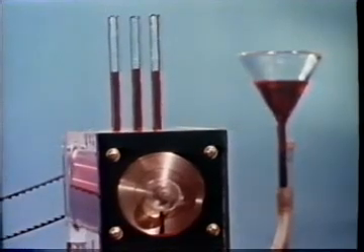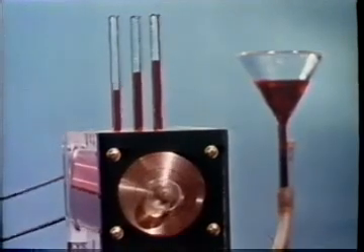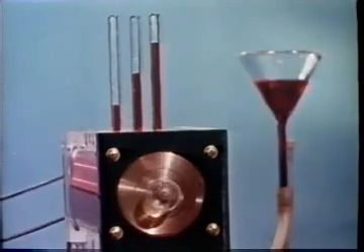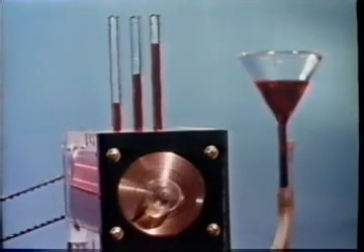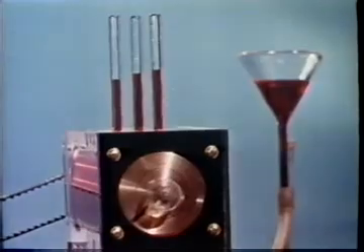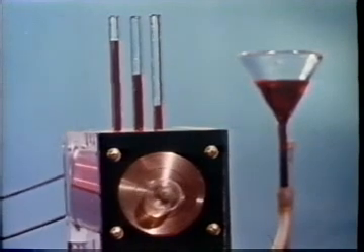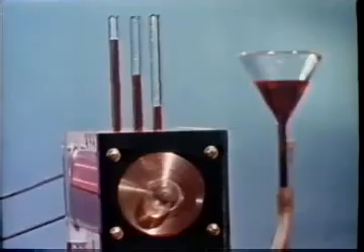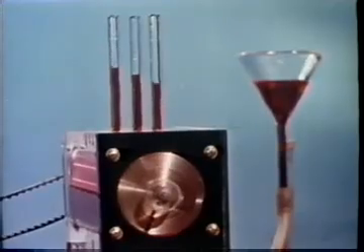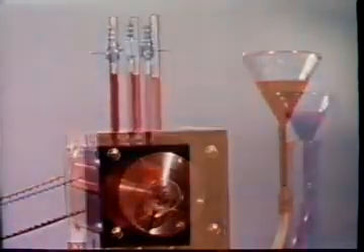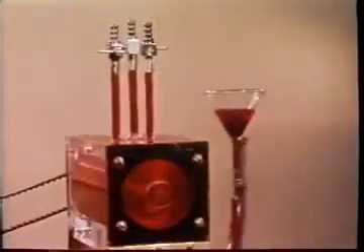In the converging channel, the pressure rises above atmospheric and then falls below it an equal amount on the diverging side. Reversing the direction of rotation reverses the stresses and the pressure distribution. Very large pressure differences can result from greater eccentricities or speeds, or if the fluid is very viscous.